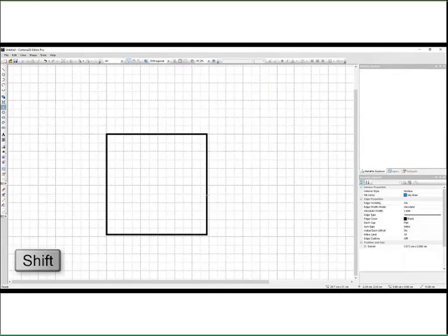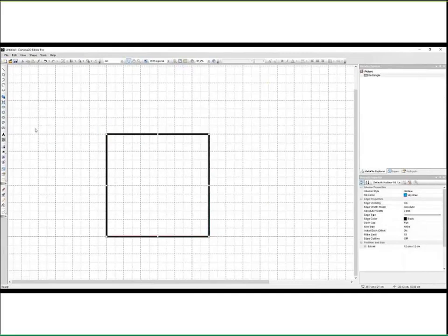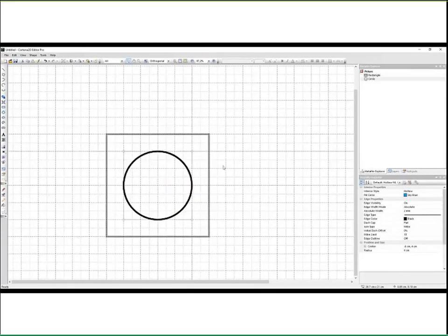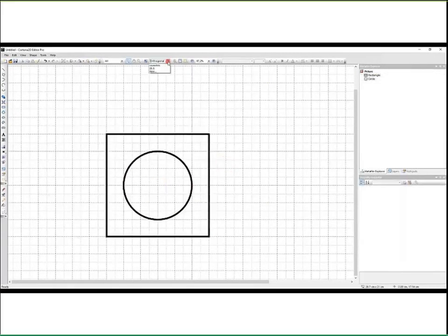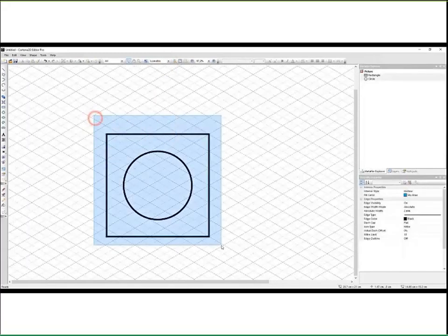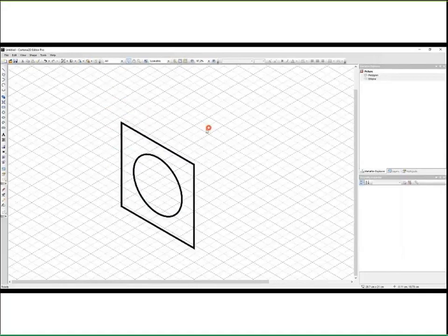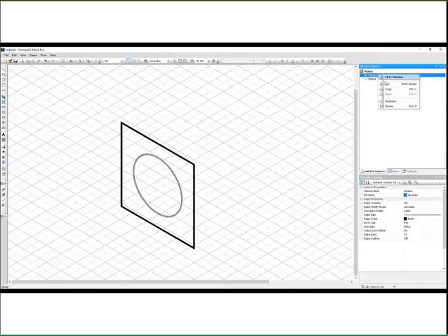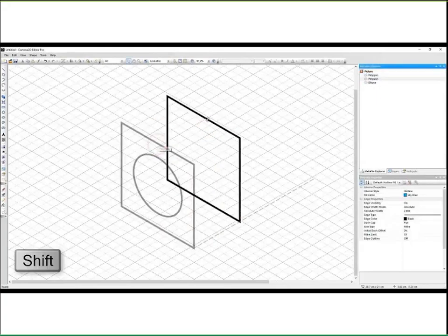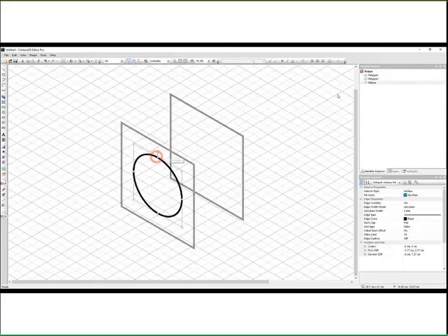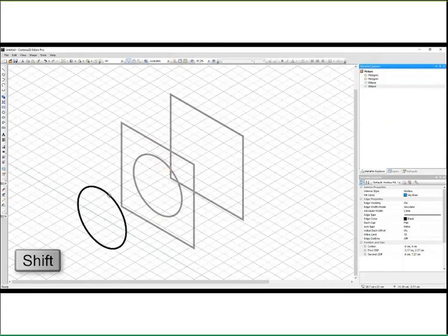Also, we'll show you how, by applying simple objects, you can create a fully isometric object. For this, we need to convert the image to the axonometric grid, and then you don't need to do anything, just start working with the objects. You have the full alignment, the centers, the dots, the points, everything works as the usual grid.